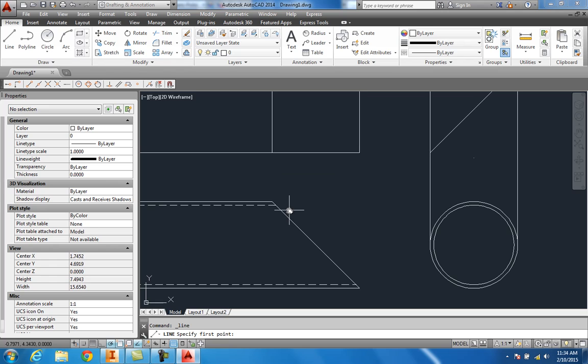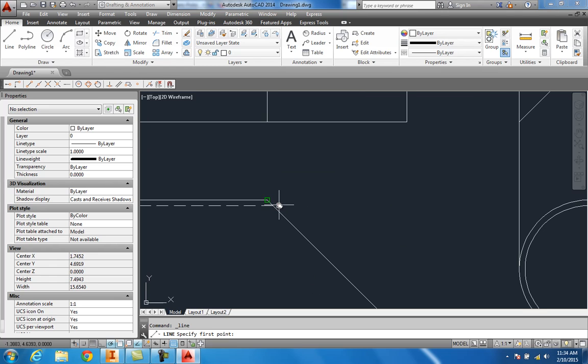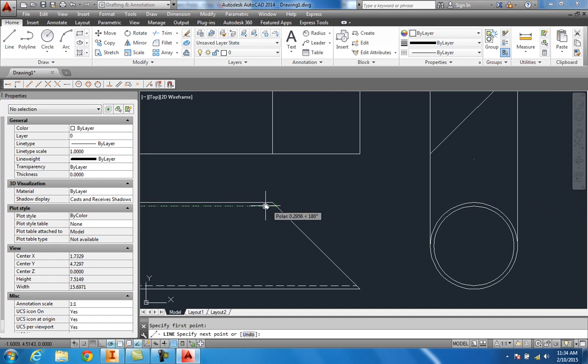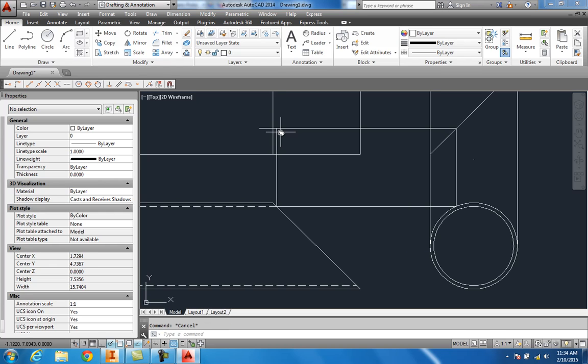So basically I want to start out about right there, at that point where the material is, where the offset is, and you come over, and as soon as you hit the part, bring it straight up. As soon as you hit that miter line, bring it straight across. Come down here, come up, and where those two points intersect, you put yourself a point in there.